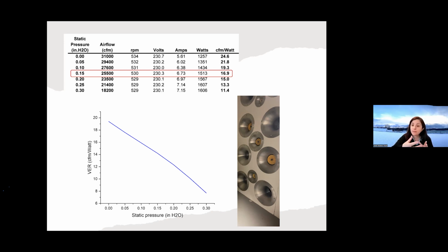For a cross-ventilated barn, there might be baffles, which increase the static pressure. If your air inlet is not designed correctly, if the inlet size is too small, it will be difficult to pull air through that barn, and then the static pressure will increase.